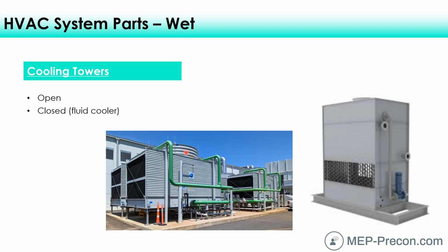What are the downsides of a cooling tower? Well, several. It's a lot of components. In the previous slide, the air-cooled chiller, everything is packaged basically in one device, and that's all you have. Here you're going to have some water treatment within your piping to prevent algae and corrosion and so forth. But also you just have more parts and pieces.